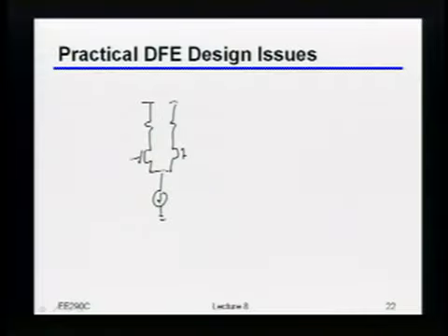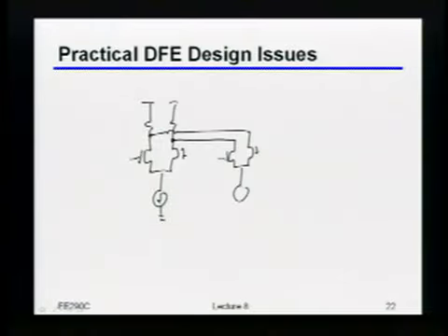All right, so if I look at my DFE summer, and let's do it with just one tap, although in reality you should keep in mind I may have many more taps than that. My DFE summer looks something like this, right? So those are my output nodes, and of course my inputs. Now remember, you don't necessarily know ahead of time which channel you're going to be operating on, at least not if you want to build a link that would work in many different possible usages. Well, that means that this thing down here is going to have to be programmable.